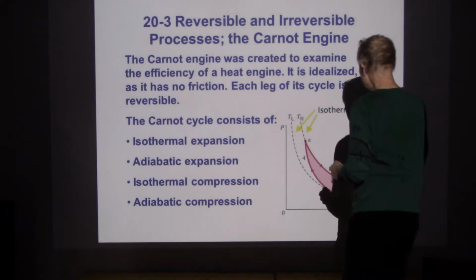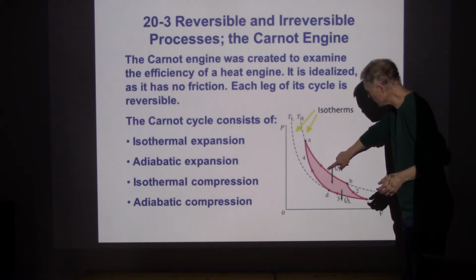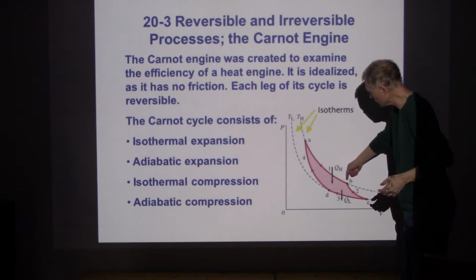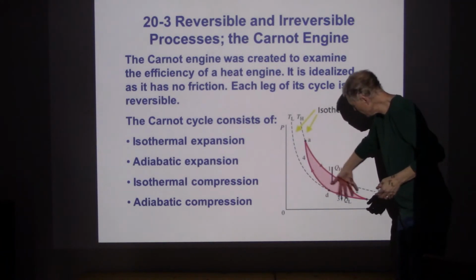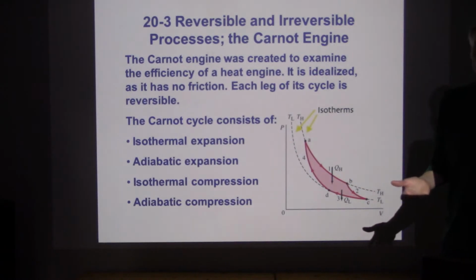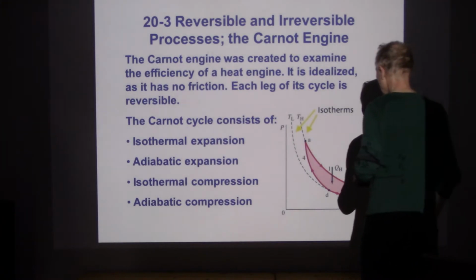So heat is coming in, and that heat is leading to a lot of work being done. You can see this expansion is happening at a pretty high set of pressures. All that area under the curve is work, and so that's our biggest portion of work right there.